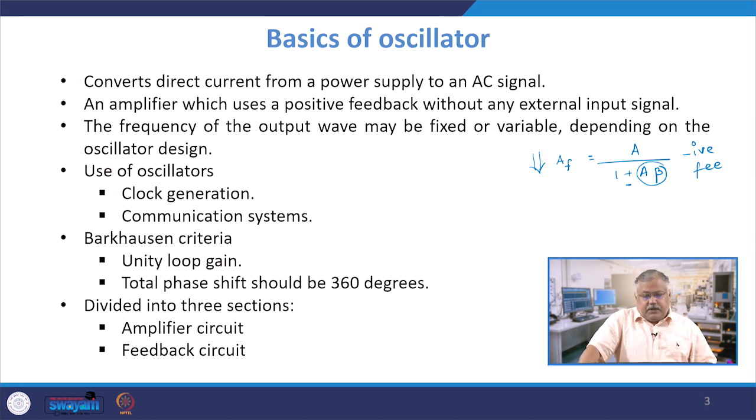Where they are used, typically they are used in clock generation. Whenever we talk in terms of design aspects, oscillators are used in all clock generation issues. But the problem with clock generation is that if you have an on-chip clock generation, since the activity factor is very high for a clock, the power dissipation levels are very high. And that is one of the major disadvantages, or maybe a challenge, of an oscillator: since it is a clock and clocks have sharp transitions, we are certain that the amount of power dissipated by the clock will be relatively very high.